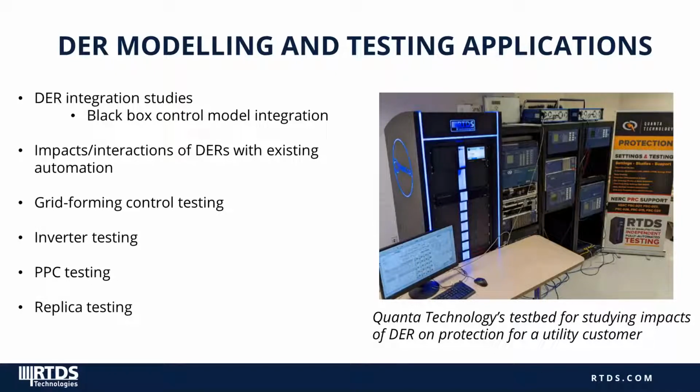Power plant controller, or PPC testing. A major justification here is model validation. So if a vendor wants to ensure that the PSCAD model they provide to the customer is accurate, they can benchmark it against the performance of the actual PPC hardware connected to the simulated utility grid.